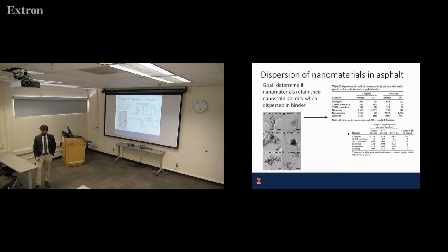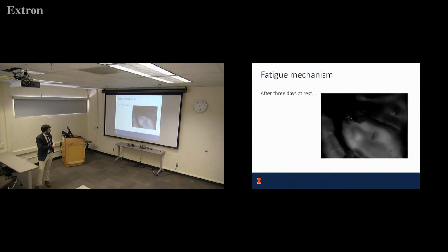We didn't publish anything on healing yet because we haven't done any formal experimental matrix on this. Basically, what we consider for healing is we pushed it until cavitation, and then we rested it back at the original position, and we just kept watching with the microscope over a rest period. We would see that generally those cavities just shrink in size. But then when we had those cracks back here, those cracks just didn't go away. I mean, that was 3 days with 0 applied load, just returning it to the original position, and we still didn't see those cracks go away.